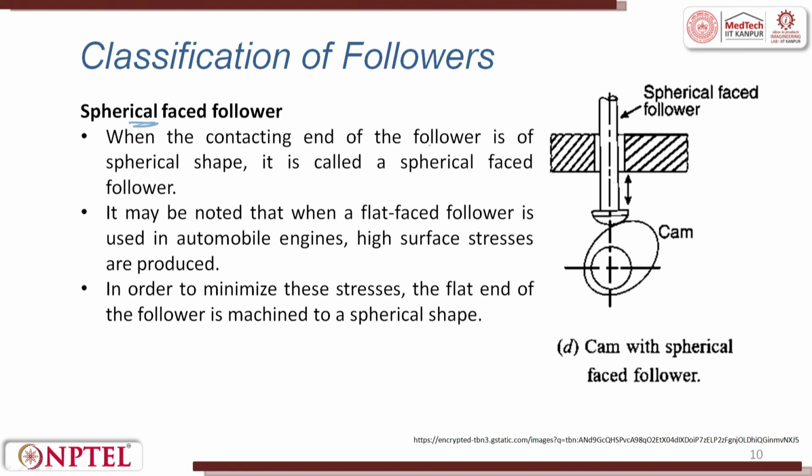When the contacting end of the follower is of a spherical shape, it is called a spherical faced follower. It may be noted that when a flat faced follower is used in an automobile engine, high surface stresses are produced. In order to minimize that, we always go for a spherical faced follower.